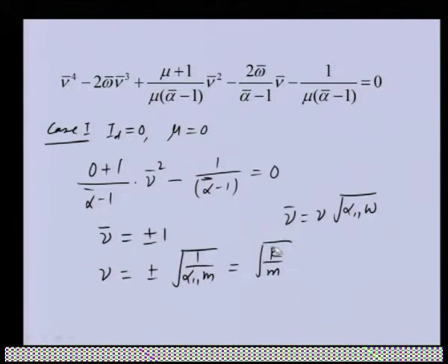So, you can see that this is the standard stiffness divided by m frequency. So, when there is no disk effect, there is a point mass, we will be getting the natural frequency which will be independent of the speed. In this particular polynomial, you can see the whirl frequency is dependent upon speed. Some speed terms are there, but if this effect is not there, then this whirl frequency is independent of the speed.